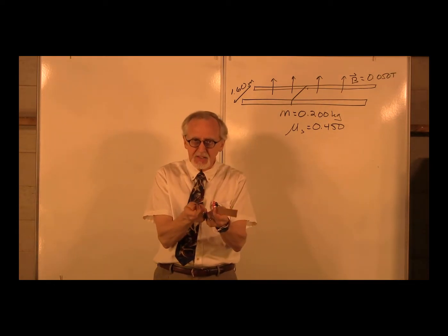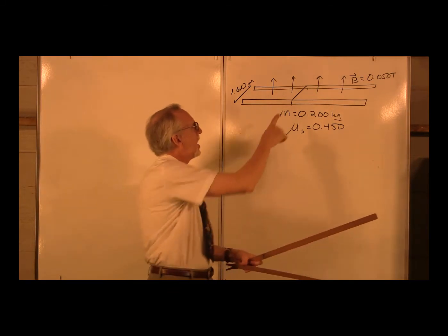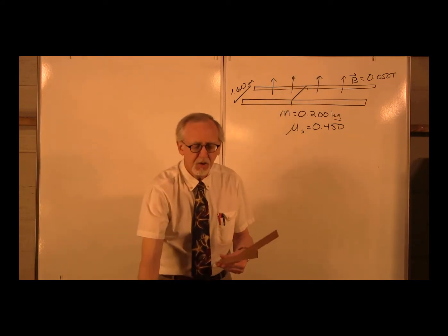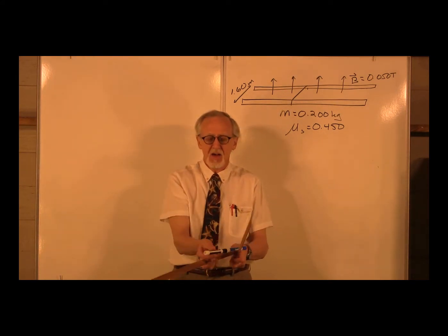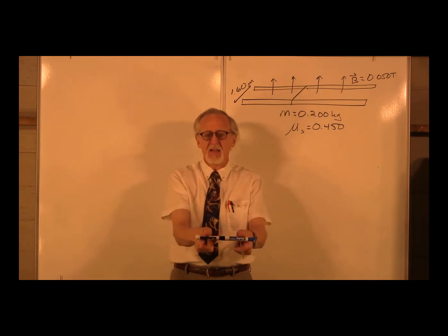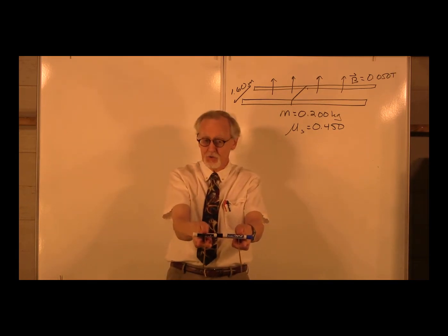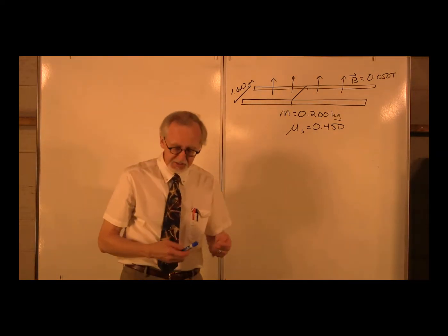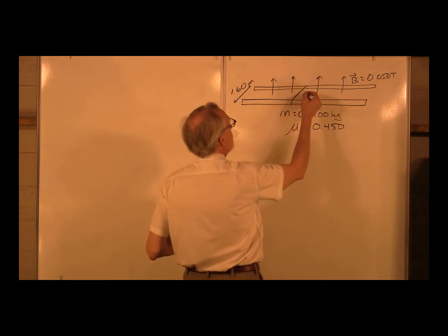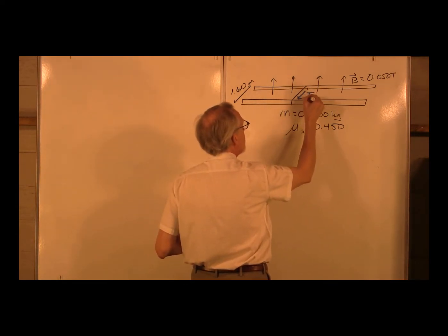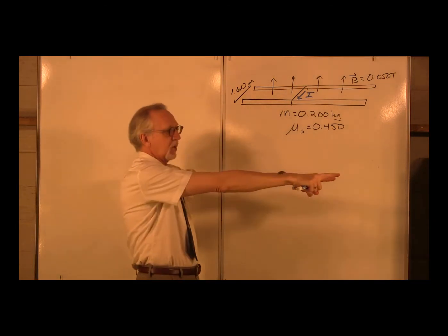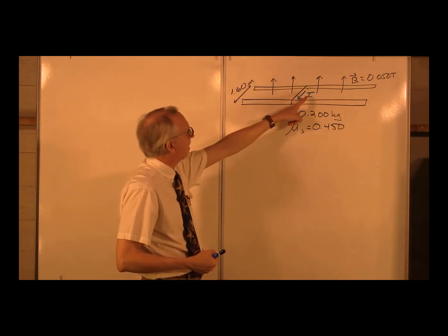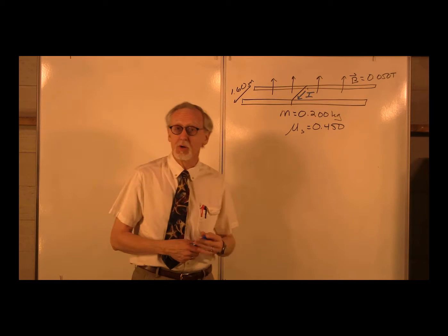Let's imagine that across these two tracks we have a metal bar. Could be more complicated than a metal bar, but that's the important idea. So across these two tracks we have a metal bar like this that makes electrical contact between the two tracks. The tracks have a voltage difference between them that causes a current to flow through the bar, let's say in that direction. So if these tracks were like this, the bar across like this has a current coming out of the board. So this electric current here, imagine, is kind of coming out towards us.